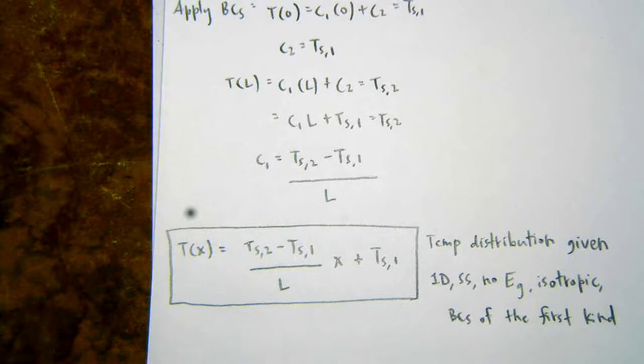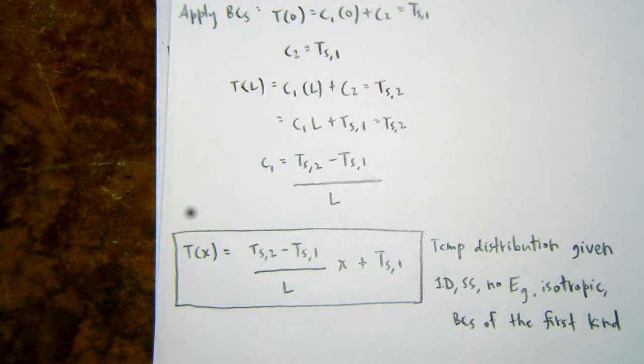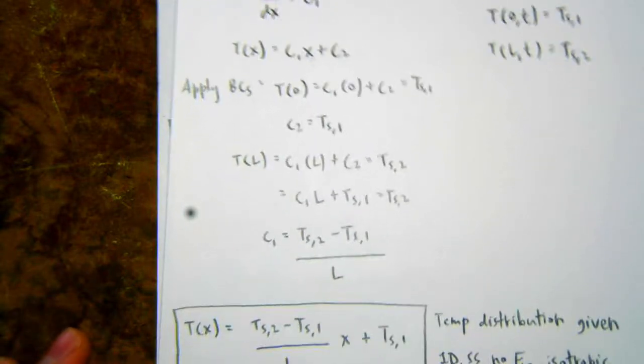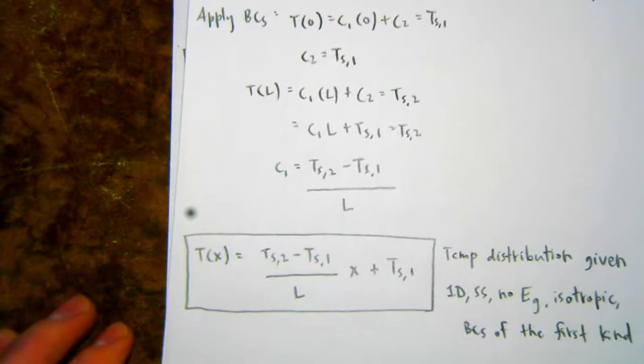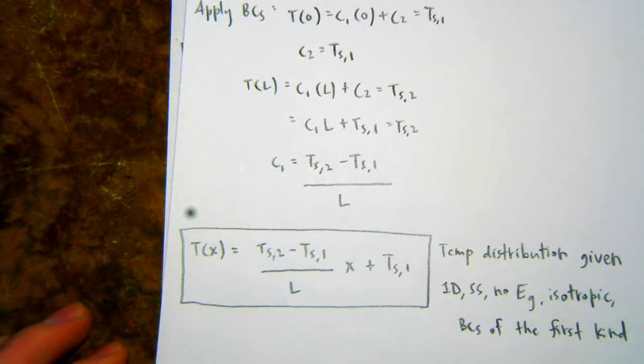Okay, so a couple of the other boundary conditions involved a derivative, right? So to apply those, I'm not going to go through it specifically, but you would need to apply the boundary condition after you integrate once. So you integrate once and you have dT/dx equals the constant. That's when you'll need to apply the other boundary conditions that are related to the derivative.